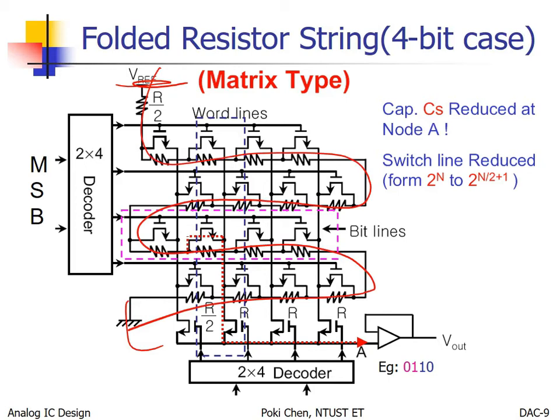If you fold it in this way, then we need two kinds of decoders. The first for MSB bits, and the second for LSB bits. So you can guess, again, never mind how many input bits, we only generate one output. All the other outputs will be off.